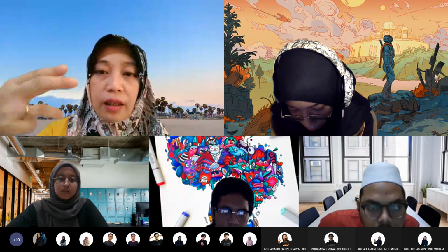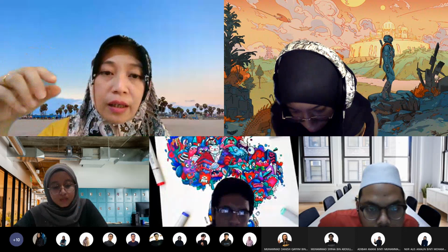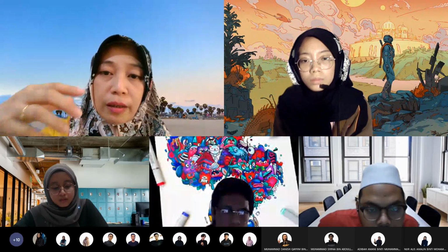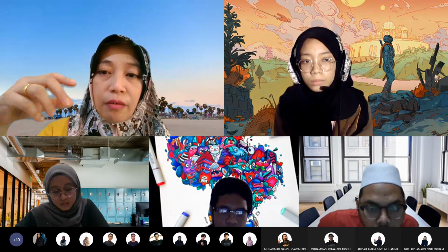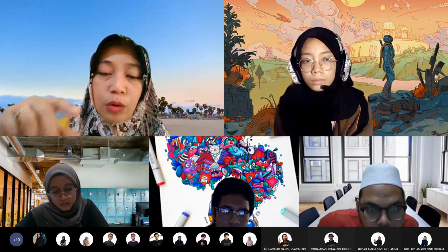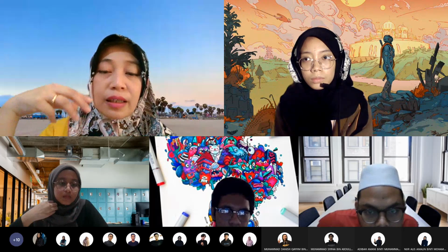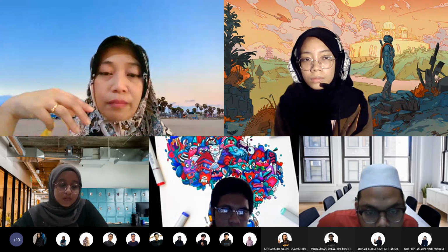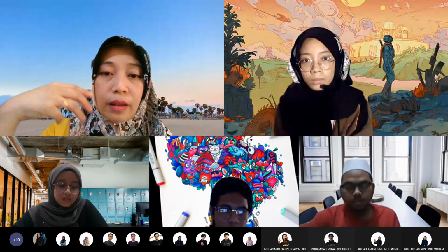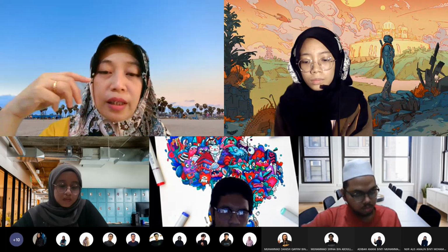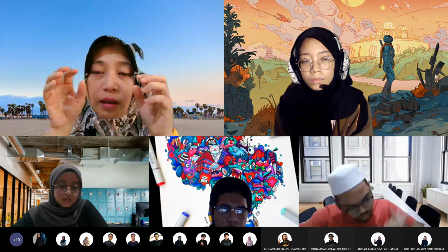So definitely at your 5th schedule, you have to refer that the distance, you know that the building is already with sprinklers, so you may say that from one fire door of the staircase to another fire door of the staircase, it can be 61 meters and more. Meaning that your fire staircase can be further. You cannot be side by side.